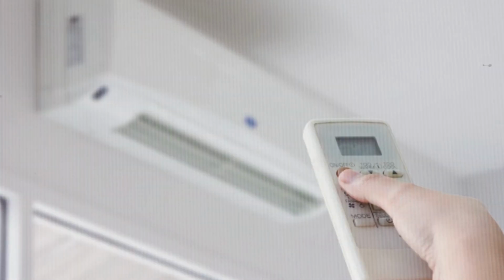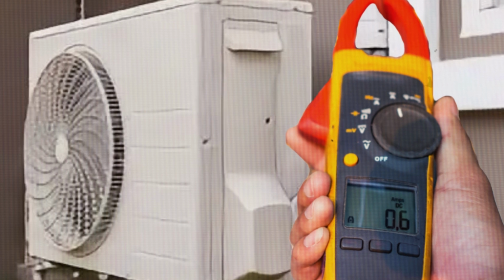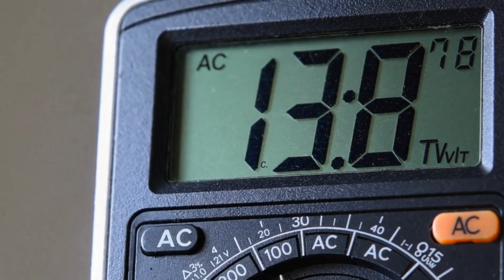If this error appears in the 1-ton Fujitsu unit, one possible cause could be a sudden voltage fluctuation in your home's electricity supply. This fluctuation can trigger the error, and in some cases, it may be temporary. To resolve this, turn off the unit completely and check the electrical supply using a multimeter to ensure that the voltage is not too high or too low. If the voltage is unstable, this could be the reason for the error, and stabilizing it might fix the unit.